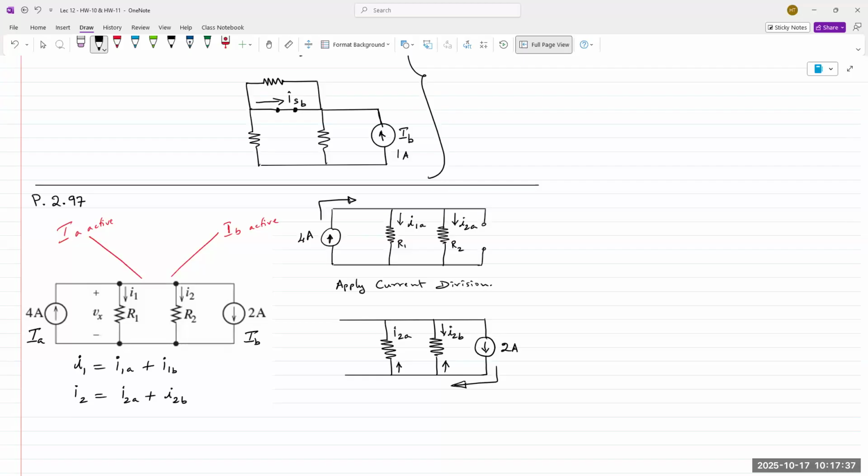If they're flowing up, then the I1 and I2, because of A and B, are going to be flowing in the opposite direction. And so when you sum up these currents, we have to ensure that we are applying a negative sign to that reference point. I1 and I2 are already given to us as flowing in the downward direction, so any mathematical equation we write must reference this direction.